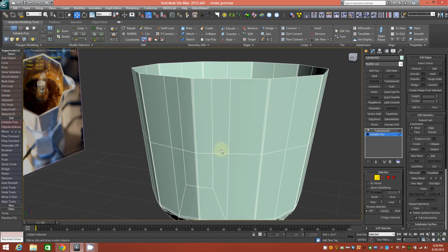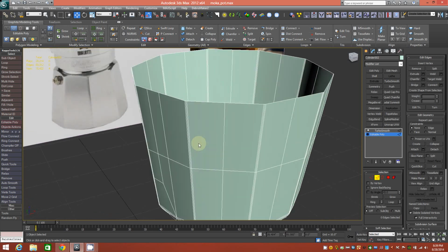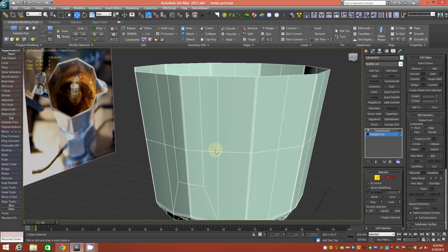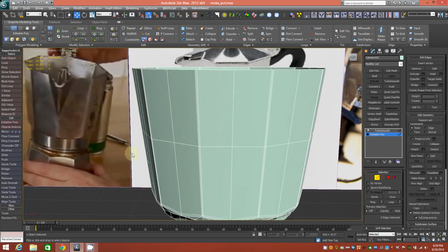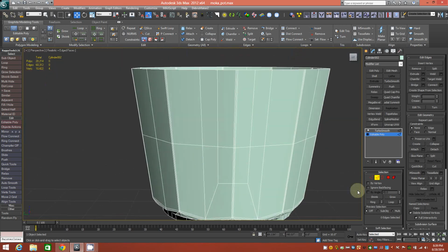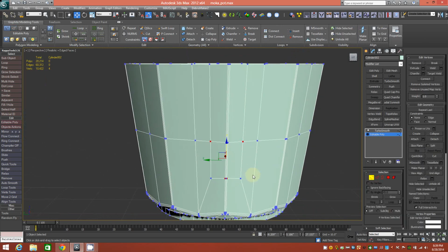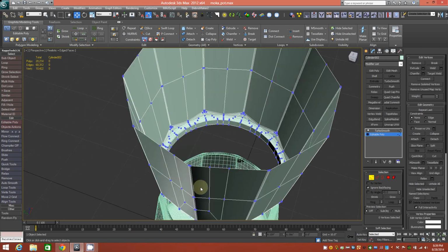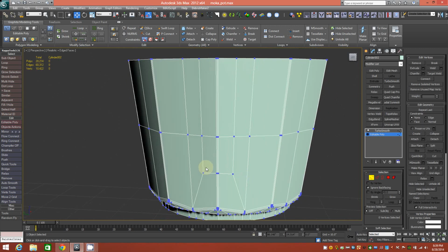Just select a U-shape group of edges, connect, and use the Build Corner tool. All right. So that's how we start off here, and the next step to achieving our V is we'll go to Vertex Mode and turn on Ignore Back Facing so we don't accidentally select anything back here while we're working in perspective.